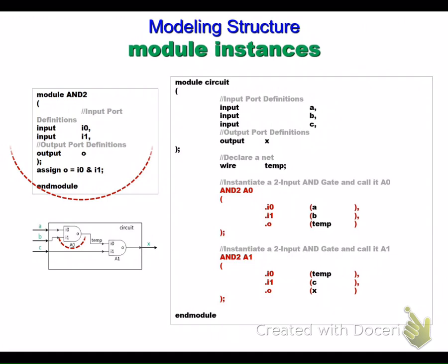Assuming that you have this AND gate, and in your design you have two of exactly these AND gates, similar to each other. Do I have to write in my design that I have this AND gate and then another AND gate, and assume I have millions of these? Do I have to repeat the code millions of times? That does not make sense, correct? I have to define it only one time, and then I will instantiate it. In another sense, I will call it.